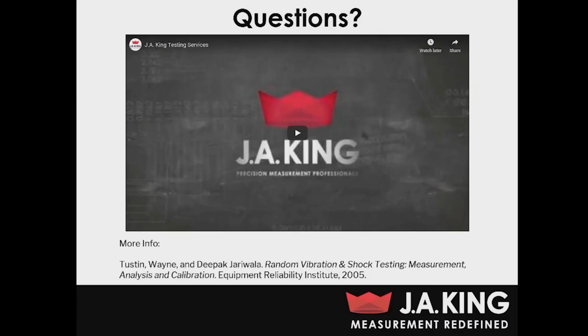Someone wants to know, what is the max payload of your shaker? Okay, so the max payload for vibration or shock testing for our shaker is actually a bit more of a complex question than you might think, because the actual weight of your DUT and fixture combination is not the only parameter to consider. It's also dependent upon the actual profile that you want to run as well.